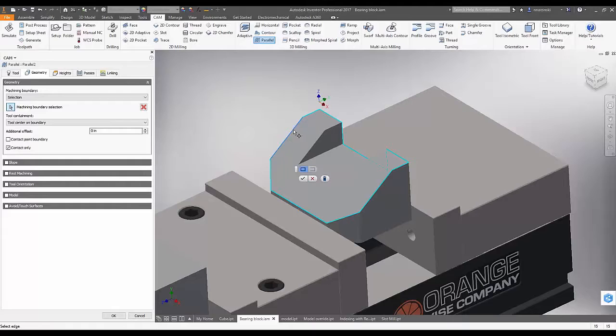That puts me in edit mode, and now you can see the dark blue line. I'm just going to go through and re-guide the toolpath wherever it veers off. So it veers off back there. I'm going to come through and select here. It veers off down here, so I'm going to reselect up here as well as right there. So now I've got that entire surface encompassed, and I'm going to hit the check mark to project that down.